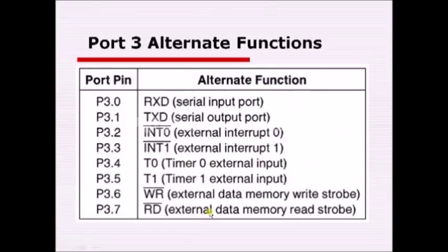So this is how we are going to use all these port pins. If I want to use any of these port pins to act as output, then we have to write some logical values into those port pins. Why? Because each and every port is provided with 8-bit flip-flops or an 8-bit register. Every pin is associated with a single flip-flop, therefore a complete port is associated with a register.